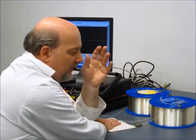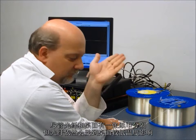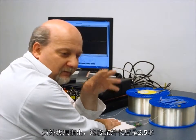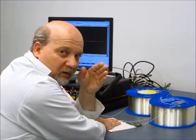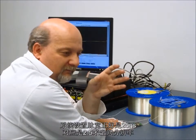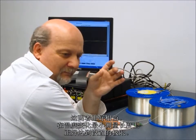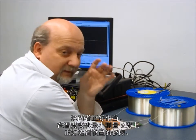Now, the fiber is going to see basically an average between my hand temperature and the temperature below the paper, so we may see something smaller as a result of this test. Also, I want to point out that this is a 2.5 meter section of fiber, and we're working with 25 nanosecond pulses, which is equivalent to a 2.5 meter section of the fiber. Okay? So we're really up to the resolution limit of the instrument here in terms of detecting this change in the temperature.